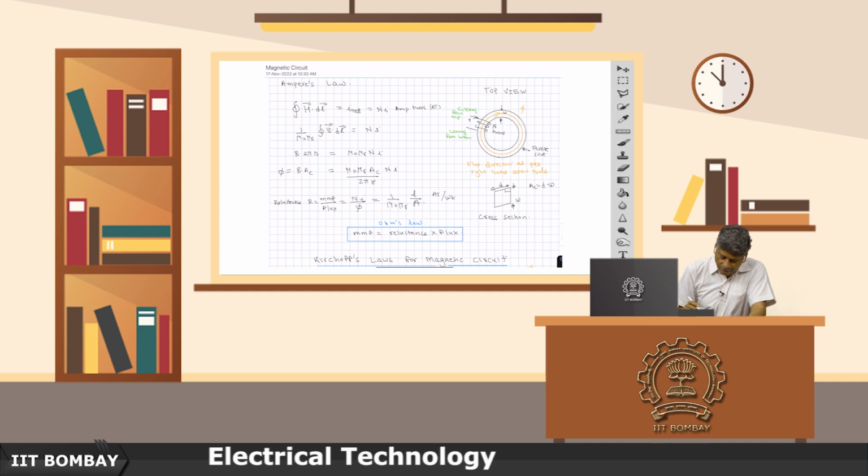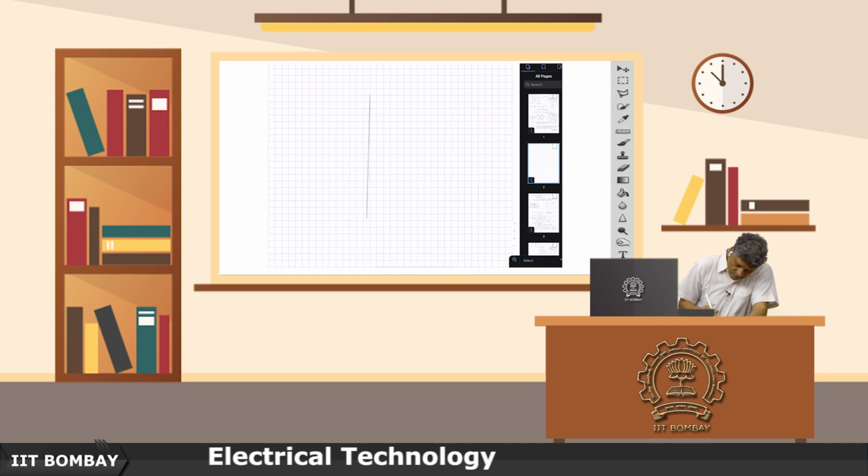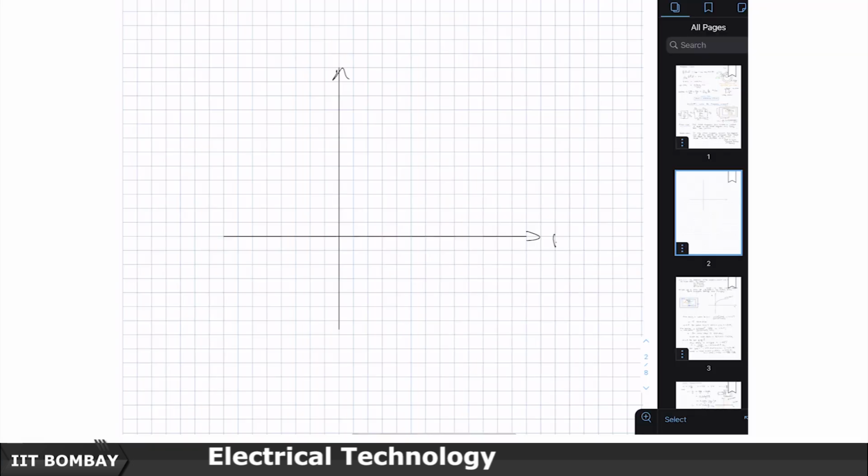Now, if you are using a magnetic material, let us say first you are in air or vacuum, then the flux density, whose unit is Weber per meter square, where Weber is the amount of flux and meter square is the area of cross section, also called Tesla, would give you a B which is mu 0 times H, where mu 0 is the permeability of the vacuum or air.